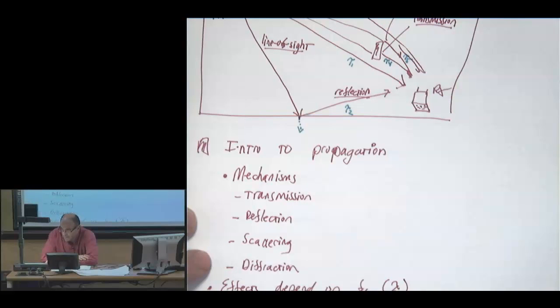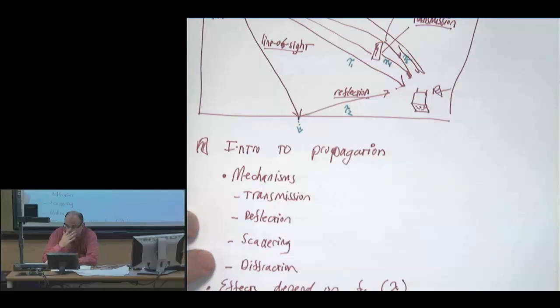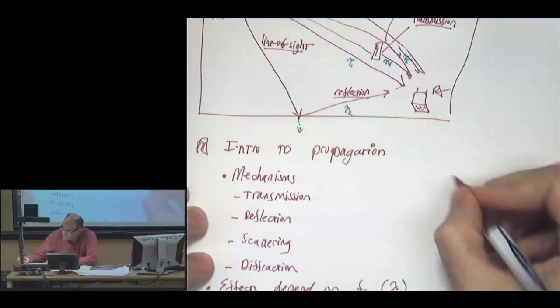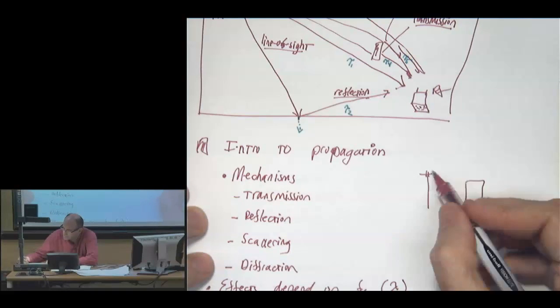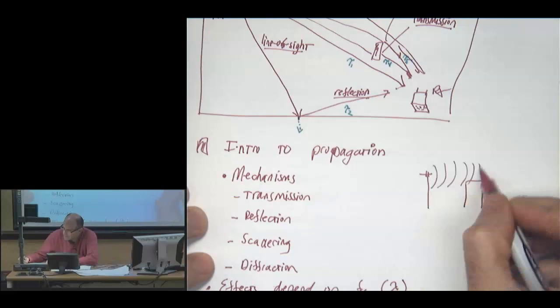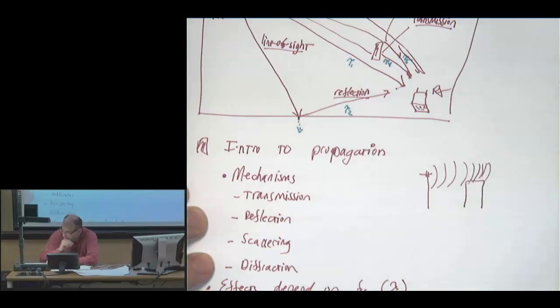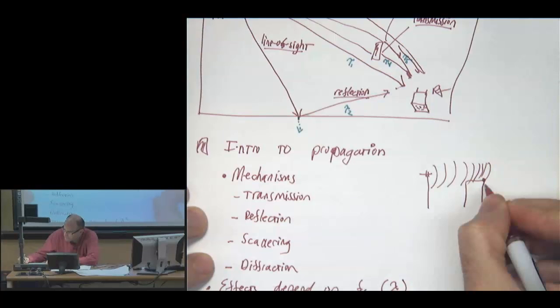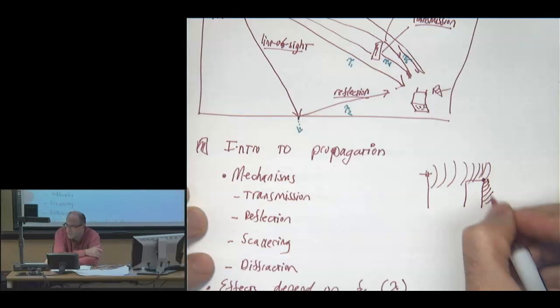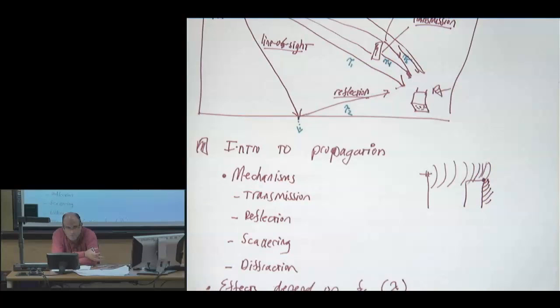And some of these mechanisms, like diffraction. Diffraction seems kind of esoteric, and really it is. It's this weird physics property, but it's actually very useful. In urban areas, especially those with tall towers, the diffracted signal is communicating like this. What diffraction says is that any of these very sharp points act like a secondary source, and there's an equation that will tell us how that signal behaves. But effectively, there's a way to model signal propagation around sharp edges. Urban areas have lots of sharp edges. So diffraction is very important for coverage in urban areas.